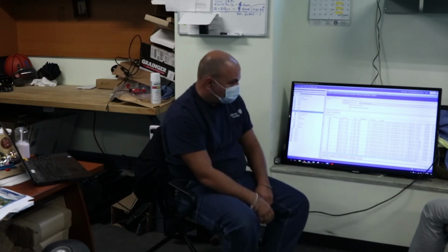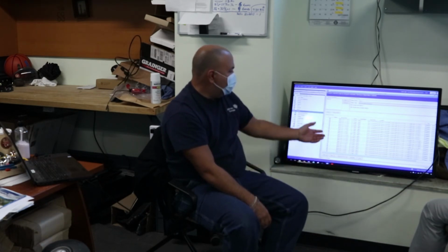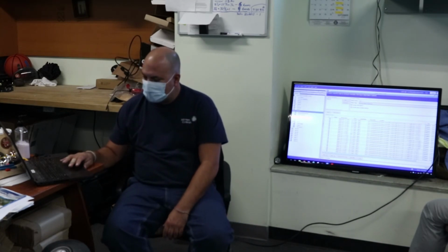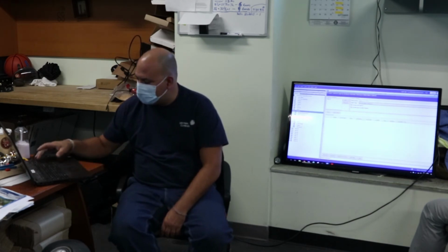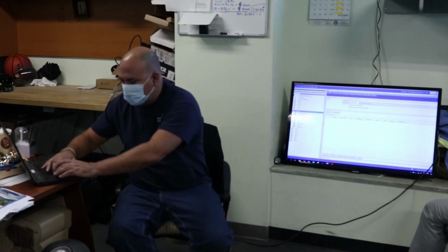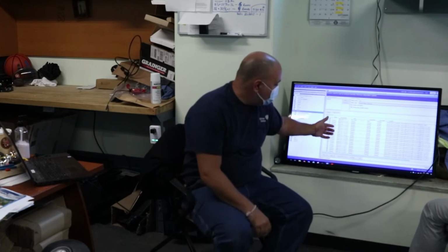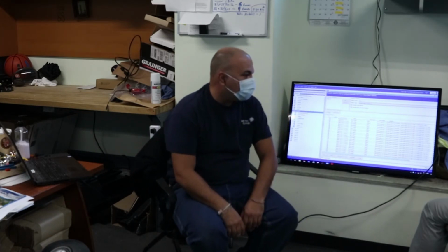Okay, but we can open like a floor plan and see what temperature is in each room. Yep, okay. It's going to be easy for us because, well, let's say you don't want to see the zone temperature, you want to see the discharge air temperature, right? Because you can't see that on the floor plan. So now I can see what the discharge air temperature is of each VAV.